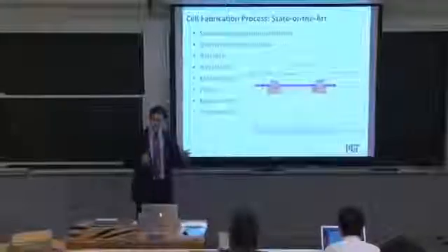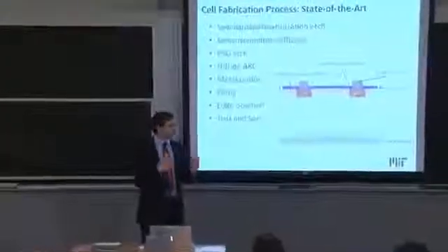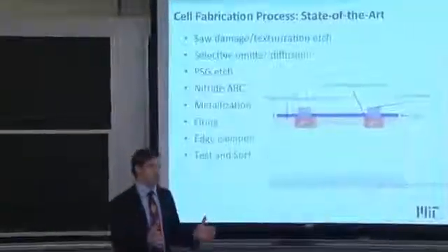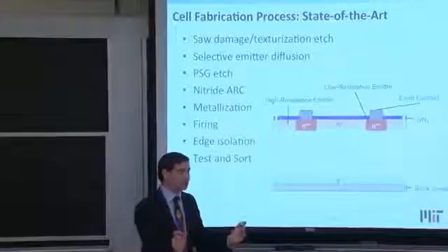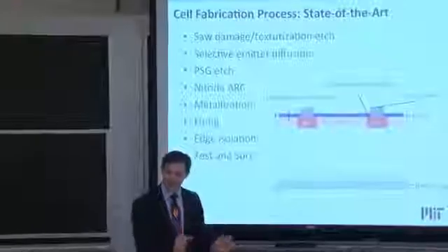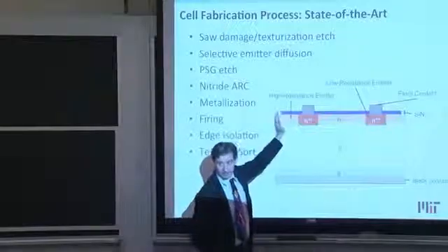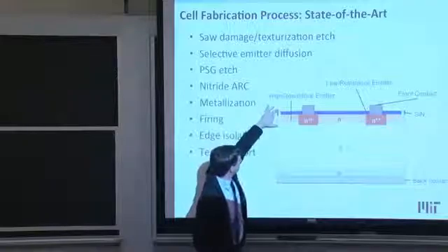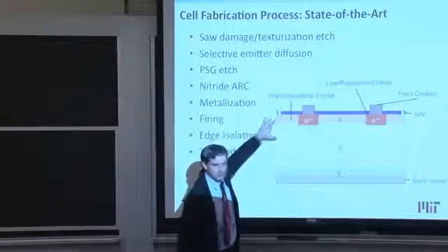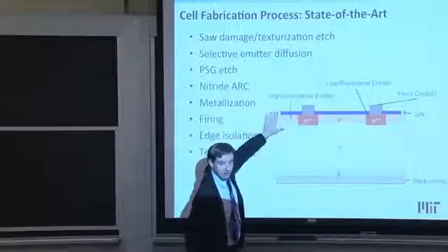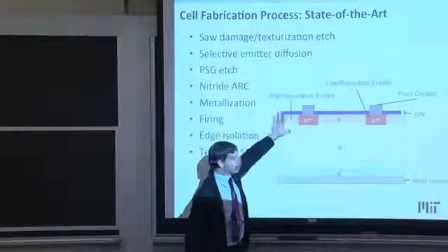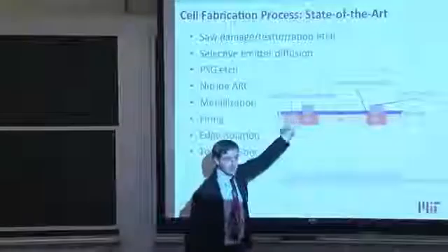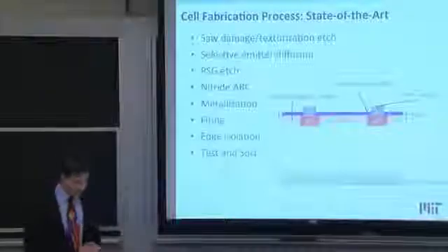Because you know your solar cell has a certain current density, let's say, milliamps per square centimeter. But if your square centimeters is smaller because you're cutting too far away from the edge, you're throwing away good material. This isn't a trench all the way through. It's just electrical isolation. So essentially, this material over here still exists. It's still hanging on to the device, but it's electrically isolated. This trench here is only about a couple of microns deep. And you're losing area. This area over here is not contributing to the photocurrent of your device. Any electron making it up into the emitter over here will just stay there and recombine. Eventually, it won't be able to be pulled out of the device.